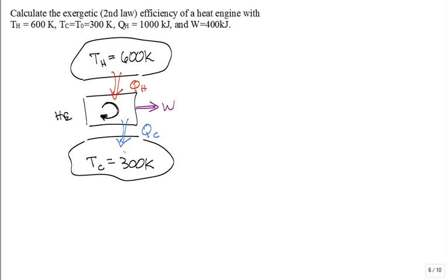Some of that heat, QH, that came into the heat engine has to be thrown away, QC, to the low temperature reservoir. All right? And so before we had an efficiency, it was called the thermal efficiency for this heat engine. What was it? Something I really want over something that I had to feed it or provide, or what costs. It's the ratio of W over QH.